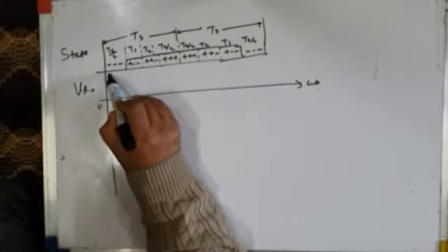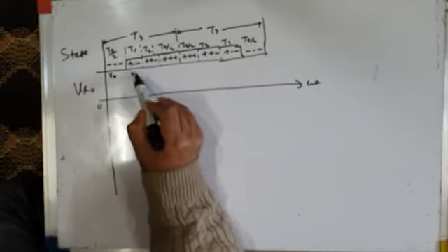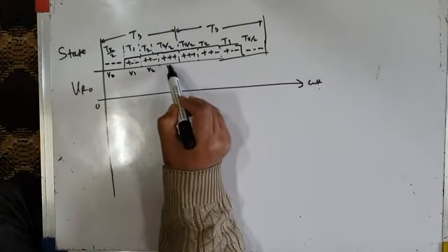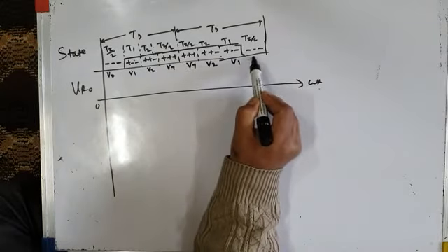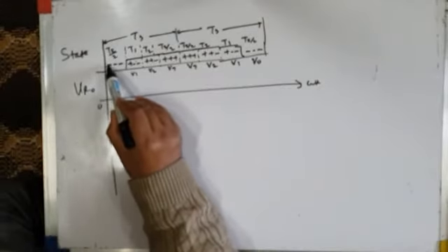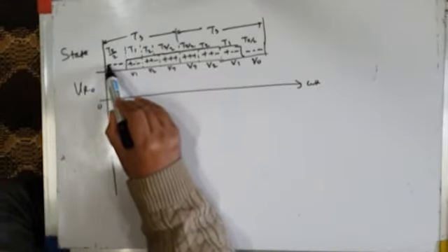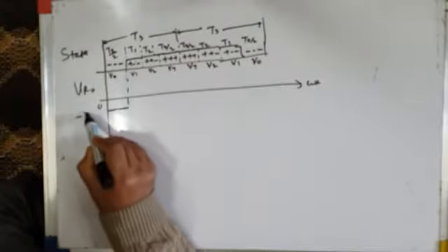During this first period, when zero voltage vector V naught is applied across the load, so this is voltage vector V naught, zero voltage vector, this is V1, this is V2, this is V7, this is V7, this is V2, this is V1, this is V naught. R phase has minus. It's minus means its bottom device is on. So what will be pole voltage? Pole voltage will be minus VDC by 2. I will write here minus VDC by 2 will be the pole voltage, right?